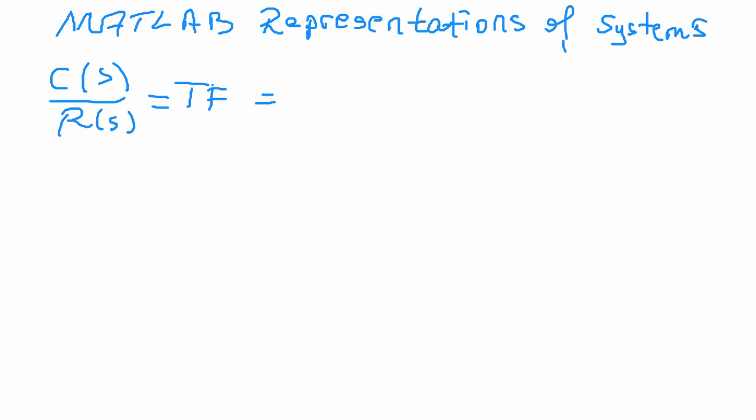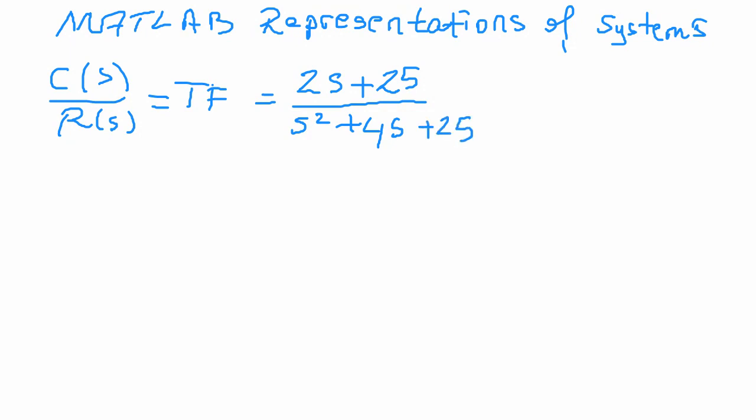Assume that you have 2s plus 25 over s squared plus 4s plus 25. What you are going to write here then is num, the numerator, in MATLAB.